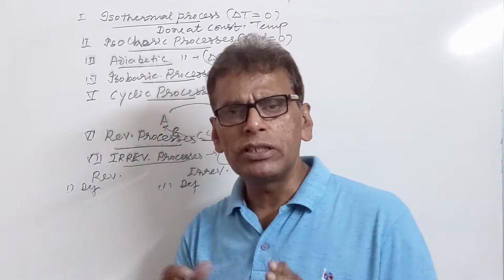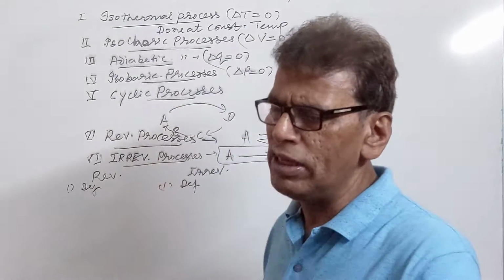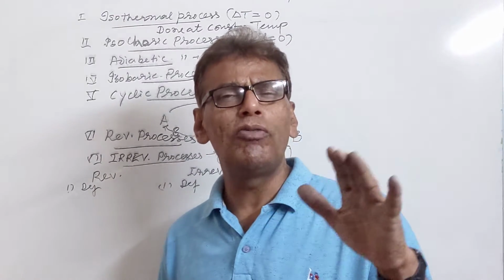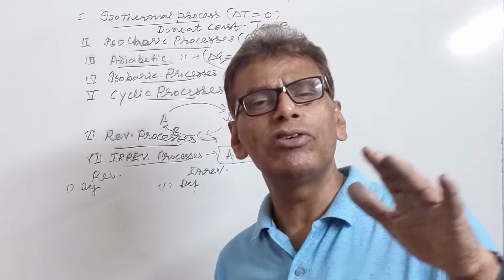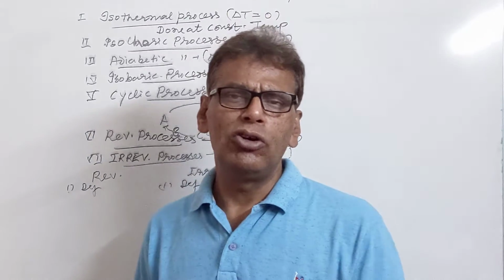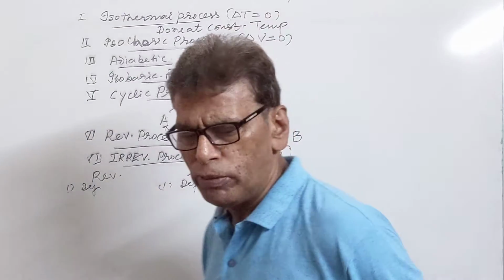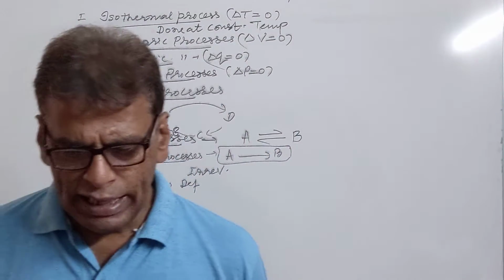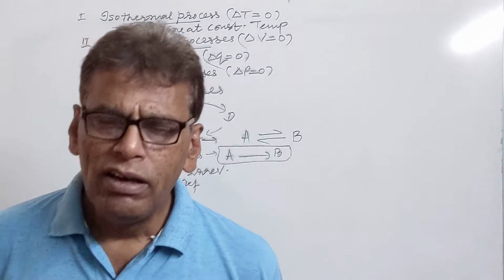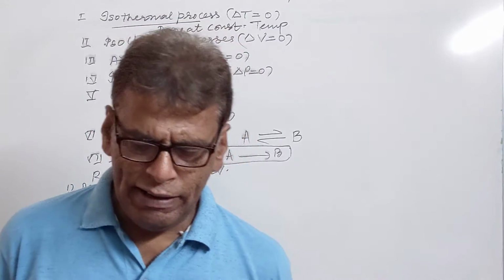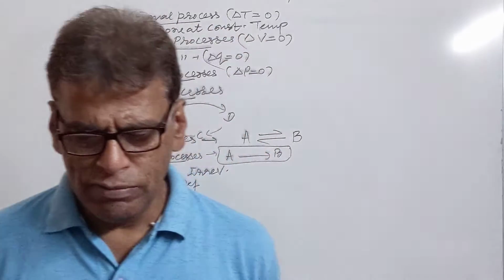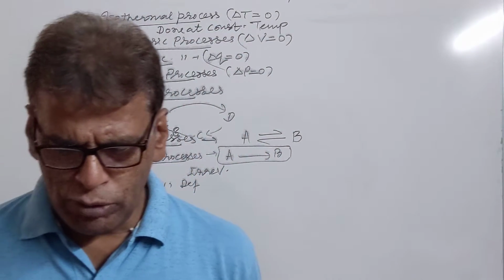Work obtained from a reversible process is maximum because no energy loss takes place during this process, because they are brought about in a very slow manner, infinitesimally slowly. But in the irreversible case, the process is brought about immediately, so heat loss is maximum, and work obtained from an irreversible process is less than maximum. It is more theoretical. Reversible processes cannot be achieved perfectly in actual conditions, so it is very much theoretical, while irreversible processes are the natural processes.